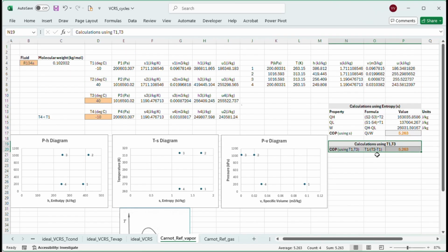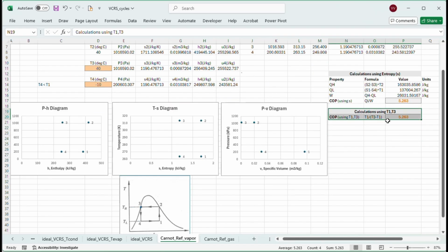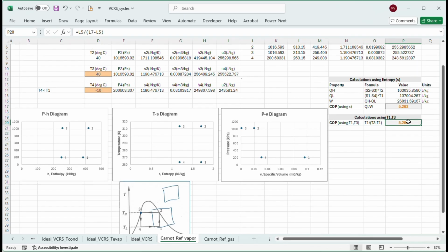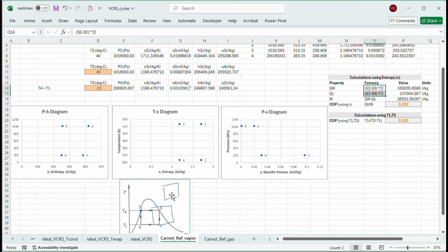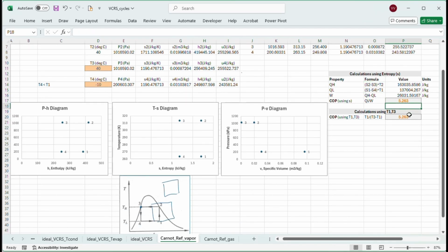Okay, so it usually doesn't matter where you are. The Carnot cycle is ideal. It can operate here, it could operate here like this, it could operate anywhere because it's just an idealized cycle. You will still get the results based on the high and low temperatures. Okay, all right. So you can see that both methods that you calculate, your COP is the same, and you can easily estimate the W using the TS diagram.